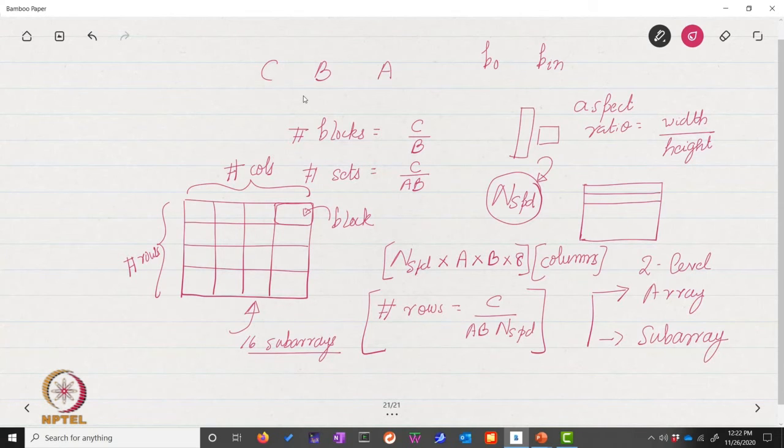This will essentially be a circuit that uses a decoder, where we use some of the address bits, and then we find out exactly which specific subarray we need to access. So we go to that subarray and read in the block from there. Since this is a smaller subarray, smaller than the entire array, its access time is expected to be faster.